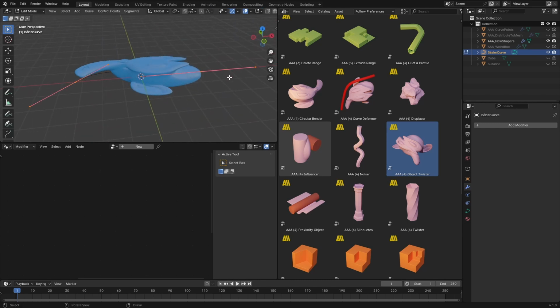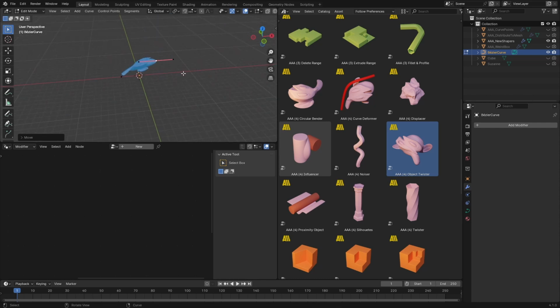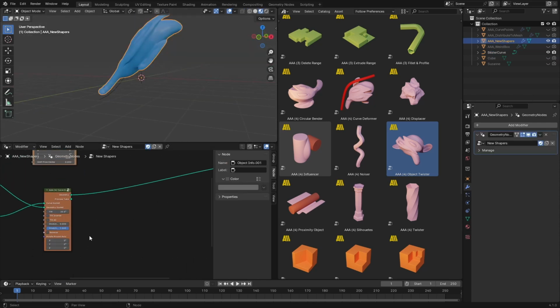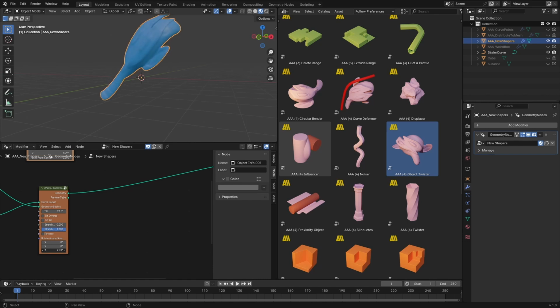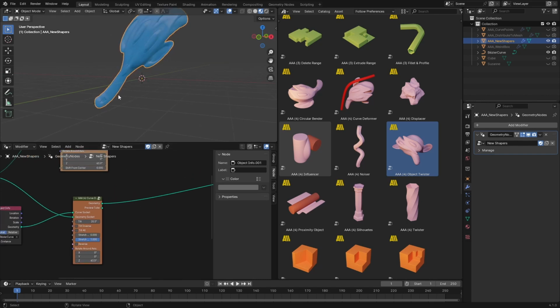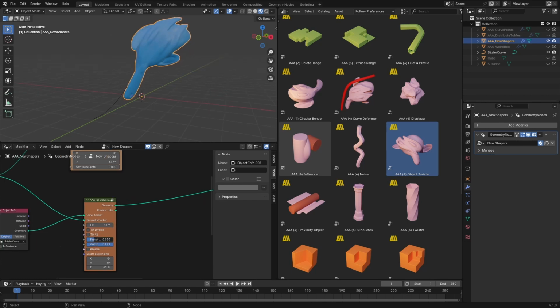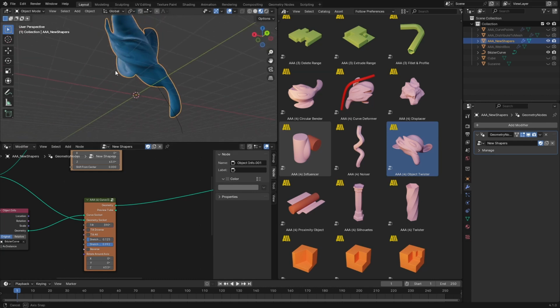If I want to play with the curve and move it around and so on, similar to the previous example, you can rotate the object around the axis. You can affect how stretched it is, so you can do something like this. You can change the tilt value. Let's pronounce it a bit. If you change the tilt value, you get something like a twister around the curve.